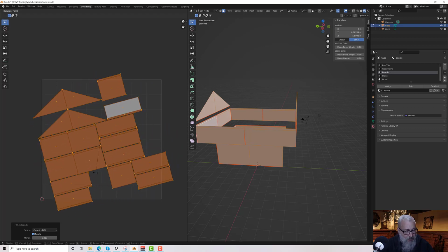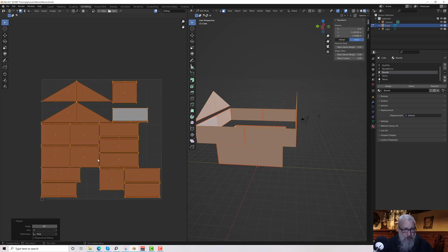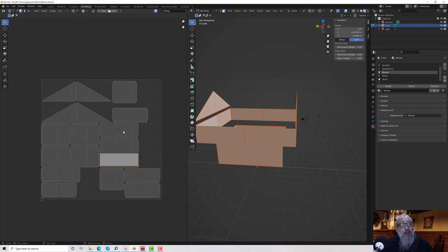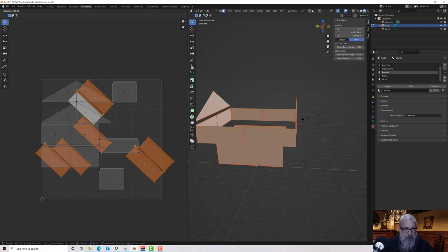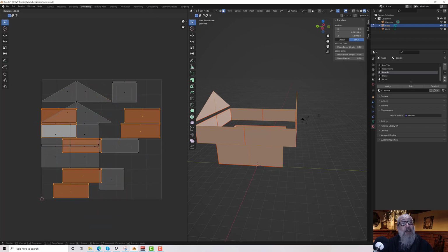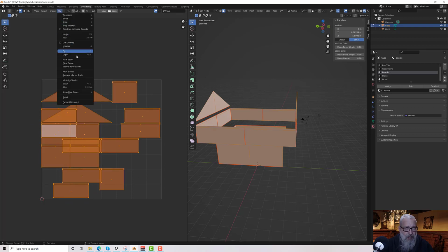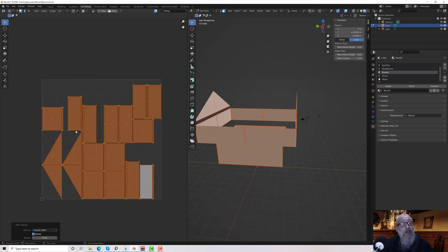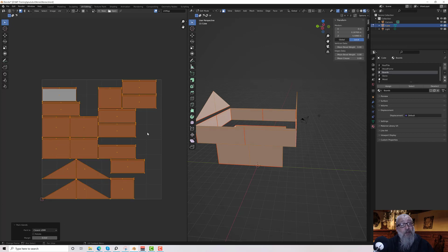And then we'll rotate it around 90 degrees with Control, and then select the ones that are upside down, that one and that one, Control L, and we'll rotate these with the R key 180 degrees, and Control to constrain, then A, UV and pack without rotate.